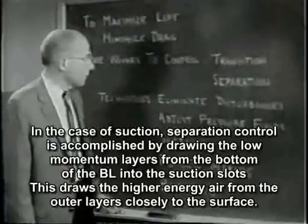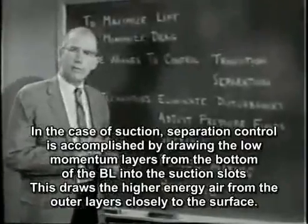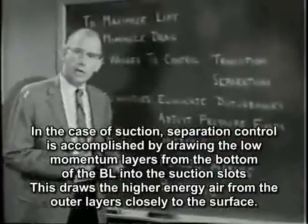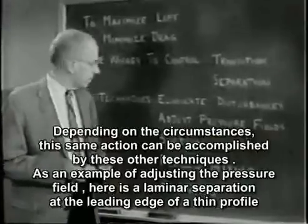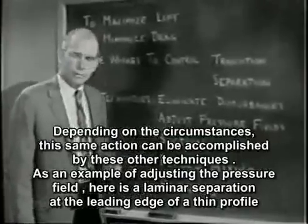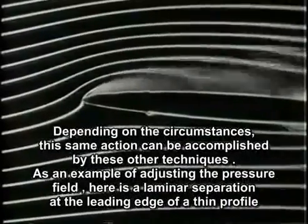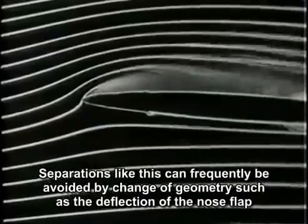In the case of suction, separation control is accomplished by drawing the low momentum layers from the bottom of the boundary layer into the suction slot. This draws the higher energy air from the outer layers closer to the surface. Depending upon the circumstances, this same action can be accomplished by these other techniques. As an example of adjusting a pressure field, here is a laminar separation at the leading edge of a thin profile. Separations like this can frequently be avoided by a change of geometry, such as the deflection of a nose flap.